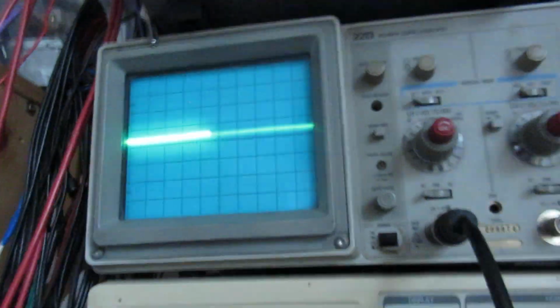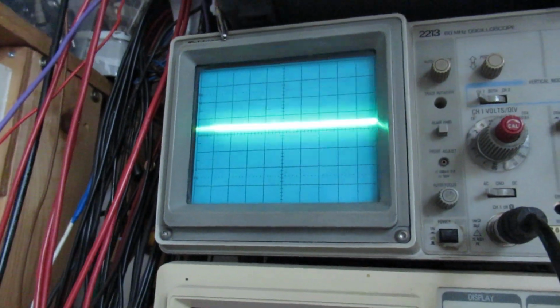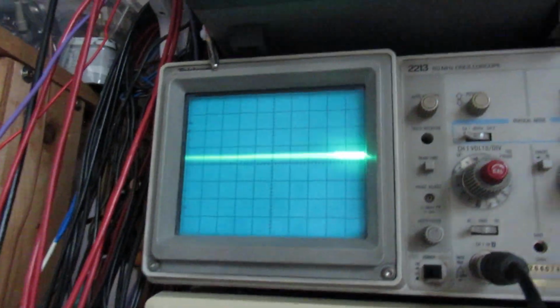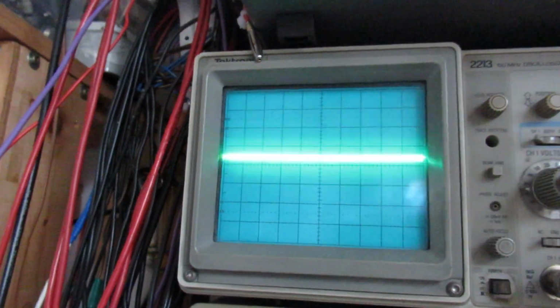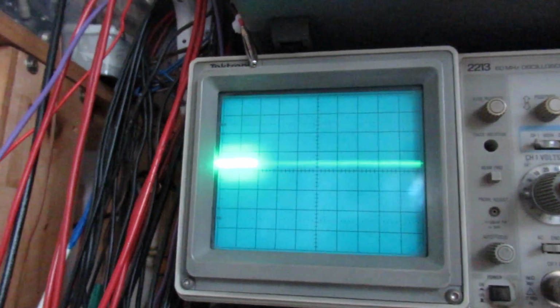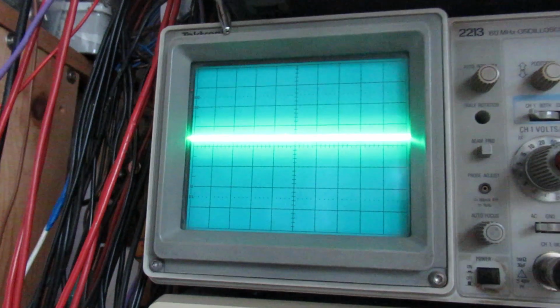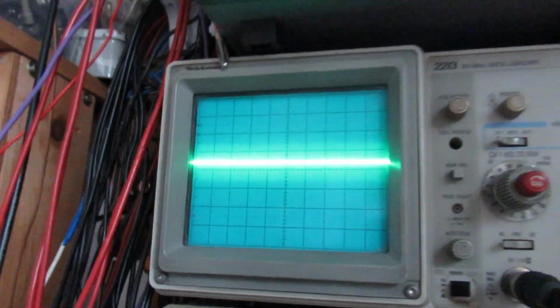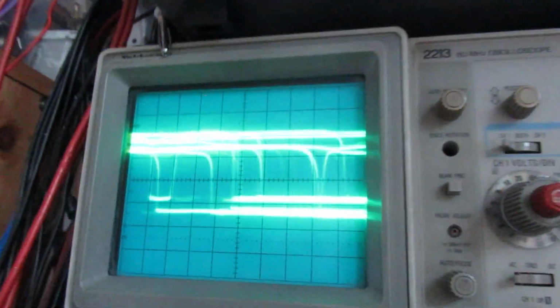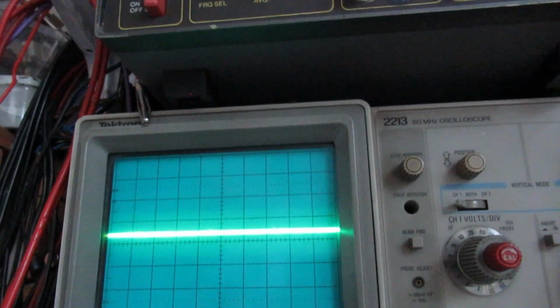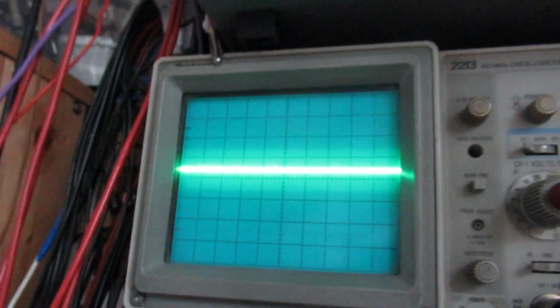Where are the oscillations visible? Now I touch with the other part of my hand another part of the circuit. So I bring down the amplification somewhat and lift up the, say, the time base to see where these oscillations are, approximately on which frequency.